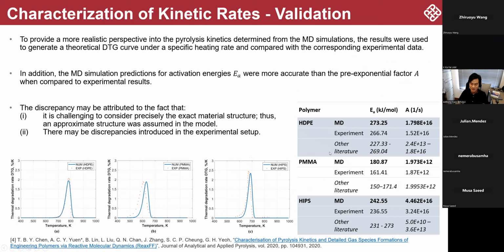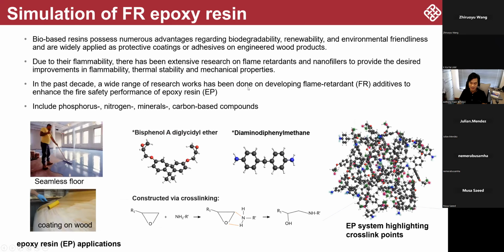On the other hand, if it involves more different chemical elements, it becomes more complex, and there will be a bit more deviation. But polystyrene, you can capture pretty well as well, mainly because the C and H reaction force field is pretty well done in MD.